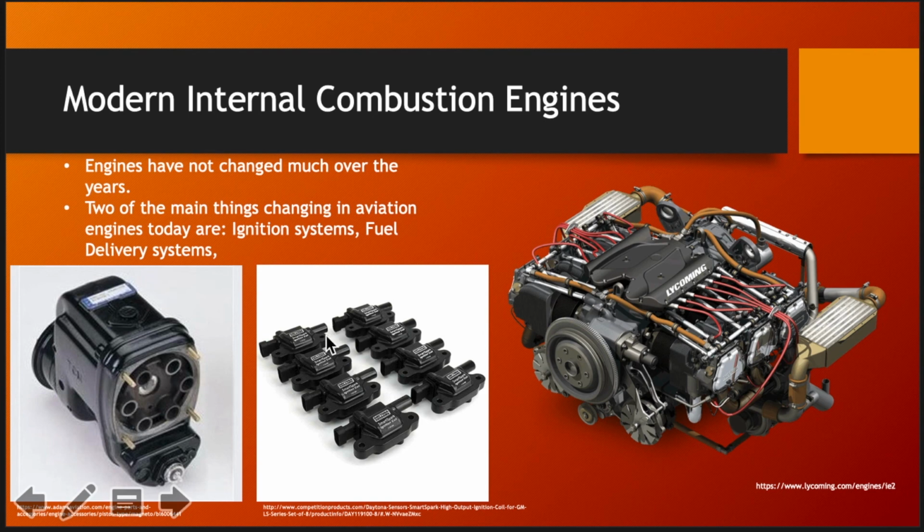With these newer engines, you can actually have a coil pack for each spark plug, and on this engine, and on all aviation engines for piston powered stuff, they're going to have redundancy, so it's going to have 2 spark plugs per cylinder in case you have a spark plug fail or you have a magneto fail. So you would actually have 2 of these. And on the newer engines, some of them are starting to come out to where you would have 12 of these guys to control the spark.